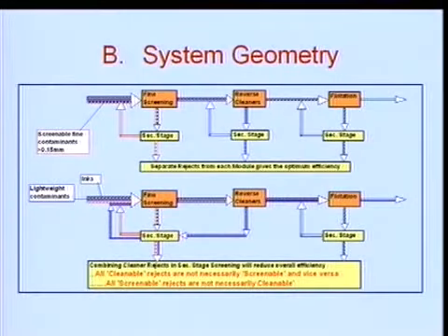Look at this example. Here we got 3 types of contaminants coming into the screening module. We have a screening, reverse cleaning and flotation modules. We have screenable contamination coming in here, which is greater than 0.15 millimeter, and then we have some ink, and we have also lightweight contamination. So, in this system, the first top system, the screen removes all the screenable contamination, that is fine, and good fiber comes back. In the reverse cleaners, we remove all the lightweight contamination, and that is fine. And in the flotation, we remove all the ink, that is perfectly fine. Now, obviously, this is an exaggerated example, but we get only good clean fiber afterwards.